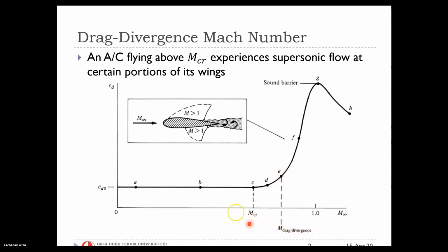So let's see what happens in this case. Over the majority of your airfoil surface you have a supersonic flow. You can observe Mach numbers of 1.2 to 1.3 in this case. And this supersonic flow is terminated by shock waves, both on the upper and the lower surfaces of the airfoil.